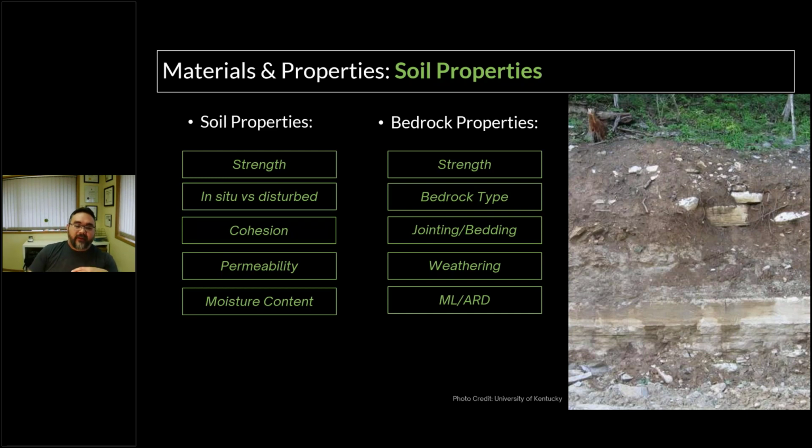So for example, if you have a colluvium apron, like an old gravity-deposited feature, and it's poorly graded or gap graded, and there's no small material to bind that large material together, if you cut it, maybe you can't cut it very steep, 1.5 to 1, 2 to 1. Whereas if that material is well graded, you can maybe cut it steeper if it's placed by a different process. Or if you have a silty sand that was placed by a fluvial deposit, and after you excavate and compact, you may shrink that material, or it may behave differently as you're cutting it.